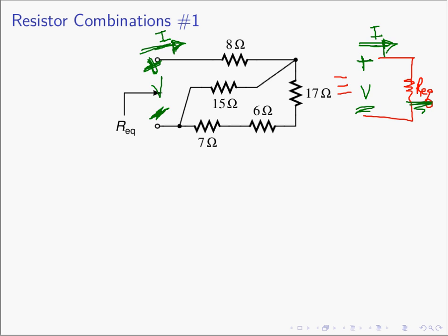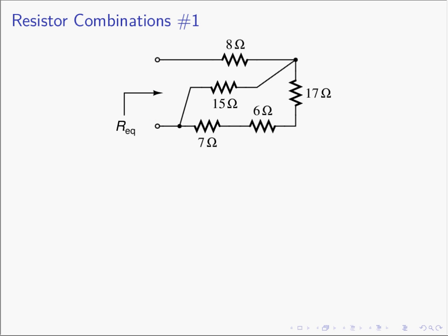So how do we do this? Well, the best way to do this, I think, is to get a set of colored pencils and just start coloring the nodes, and that makes things a little bit more apparent. So we'll color all of this node. Everything along this wire is the same energy level, so it's the same node, so we'll make it orange. Then take a different color and just start over here, and you just color the wires until you hit a circuit element. When you hit a circuit element, the other side of the circuit element is in general going to be a different energy level, and that's going to be a different node. So just go through the circuit, coloring all the nodes, so you can tell them all apart.